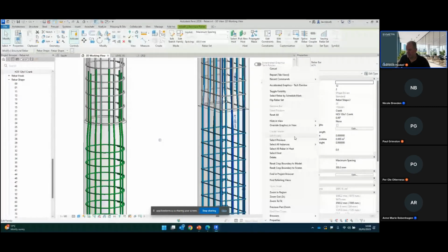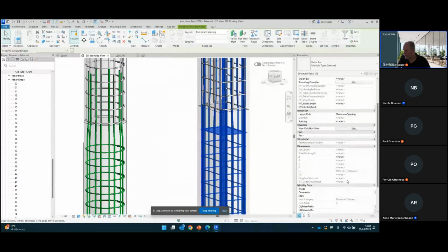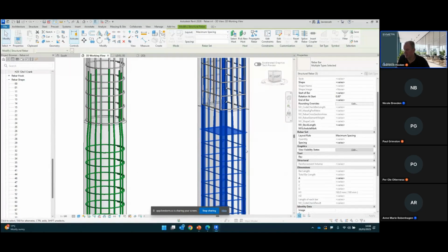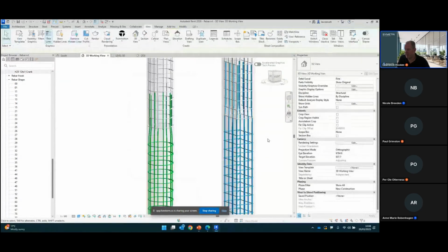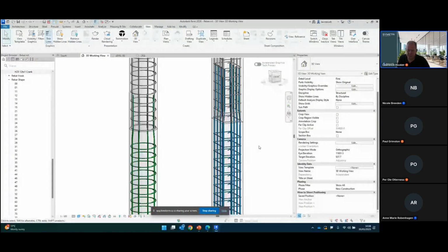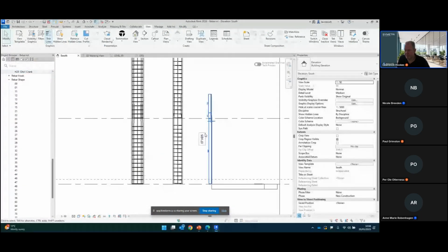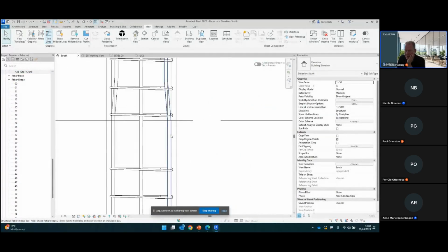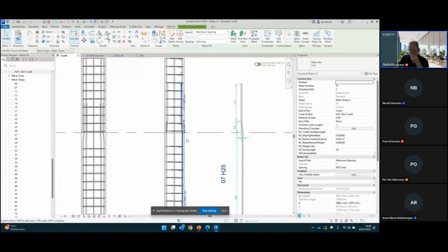And here it is. You can now see we have all of that bar cranked. Now, to help us see this a bit better, I'll select all of the rebar inside that, and we'll make sure that we can actually visualize that. So we'll go to the view visibility states, and I can see here I am in fact viewing that unobscured. Now let's just take a look at some other settings in here. So I'm just going to switch into the south elevation. Okay, and straight away here, if I zoom up, you can see that we can now preview our rebar cranks.